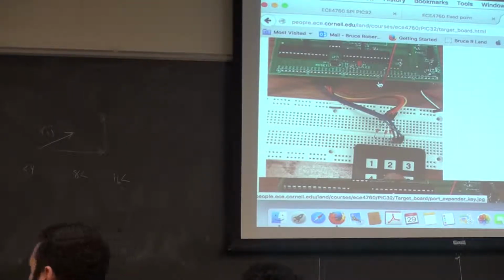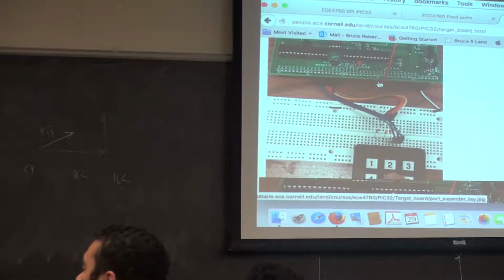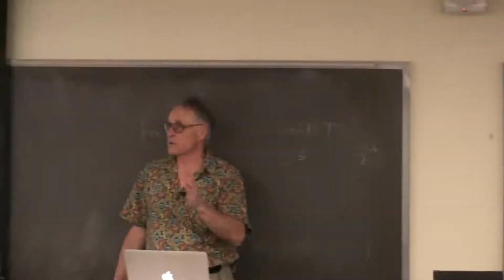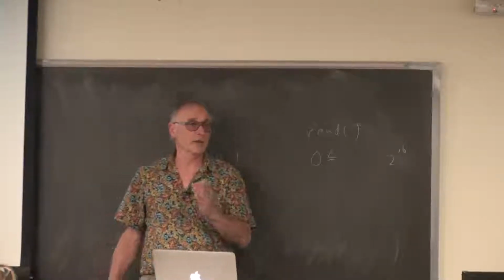Yeah, you can't interrupt, and so you have to explicitly lock out the timer 2 interrupt, which runs the DAC while you're doing the keypad read, which only takes a couple of microseconds, so you can do it and not miss an audio sample, or at least only have a little bit of jitter. You probably won't notice one audio sample that's off by 2 microseconds.